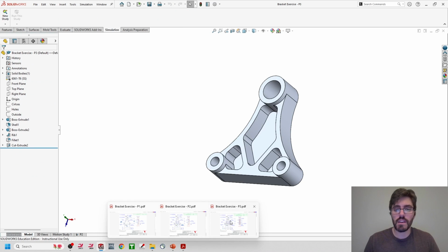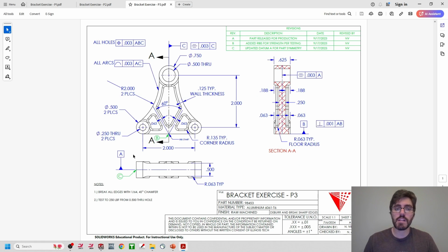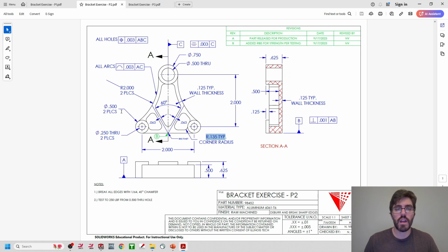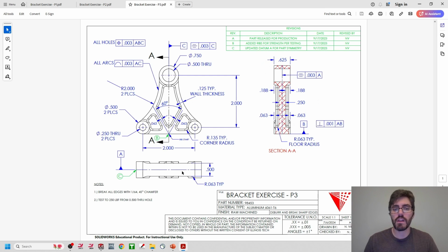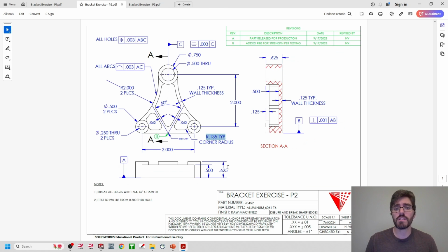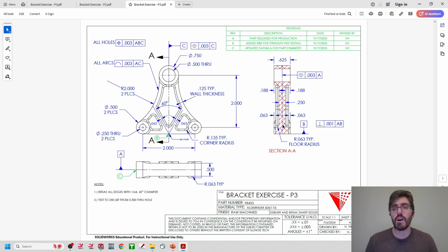And there are a couple additional details as we look at this new blueprint. We can see that the datum has changed. It's gone from P2 and P1, where the datum was at the bottom of the part, to now changing the datum to the midpoint of the entire model, and we are going to try to maintain some form of symmetry by this GD symbol up here and right here, so that the part is symmetrical from one side to the other. And this is really going to make this part as strong as it can be, because we aren't relying on the strength of maybe one flat backside wall, where now we are basically creating a cross section, like what we would see in construction or other building materials where you're I-beaming something out and you're really trying to make it as light as possible and as strong as possible as well.